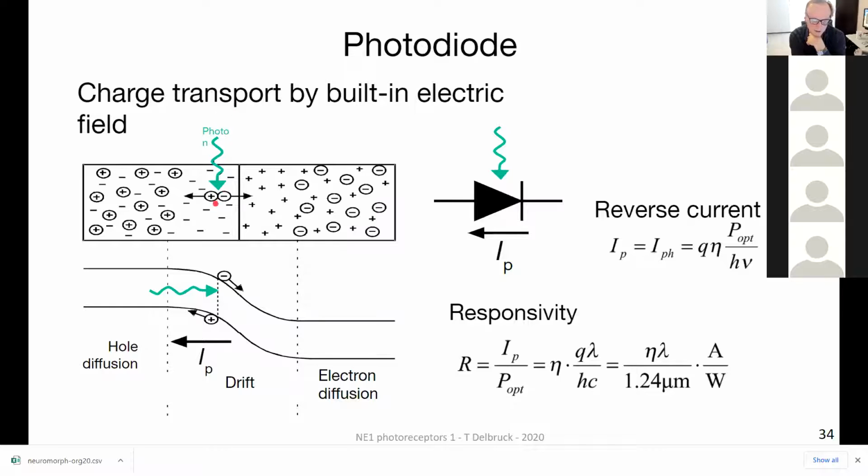So what happens if a photon shines on here and makes an electron hole pair? This electric field will rip the electron and hole apart and take them back home. Remember the one thing that I tried to teach you about that: carriers go home. The electric field always pulls the carriers back to their majority region. So the electric field here, which is opposing the diffusion of these holes, is pointing back to the hole region, so it'll pull the hole to the left and the electron to the right. So if you shine light right on the junction, it'll create electric current. Basically, 1 unit of charge for each photon that you can actually collect. Not 2 units, 1 unit.